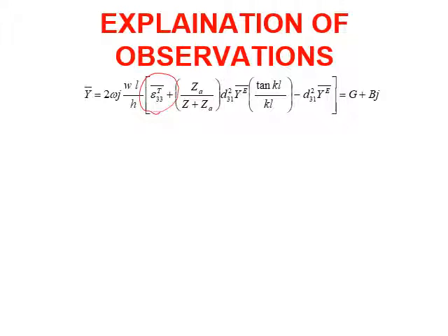Similarly, Z_a is the mechanical impedance of the PZT patch, Z is the mechanical impedance of the structure, d31 is the piezoelectric strain coefficient, and Y^E with a bar on top is the Young's modulus of elasticity of the PZT material. What does E indicate here? E indicates that it is measured at zero electric field. Now kappa, tan(kl) by kl: this is the wave number, and l is the half length of the patch.